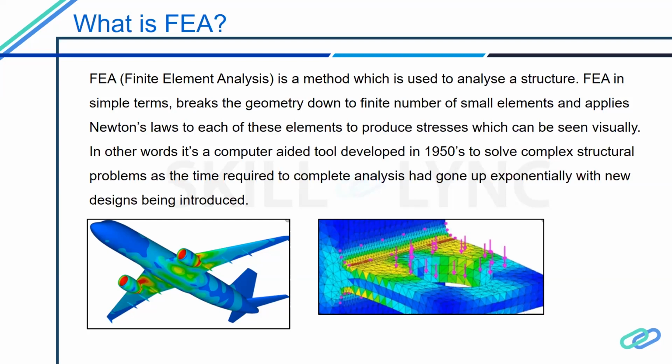You can model the entire structure in FEM software like PATRAN, apply the loads that the structure will be subjected to, and then determine stress or strain results.